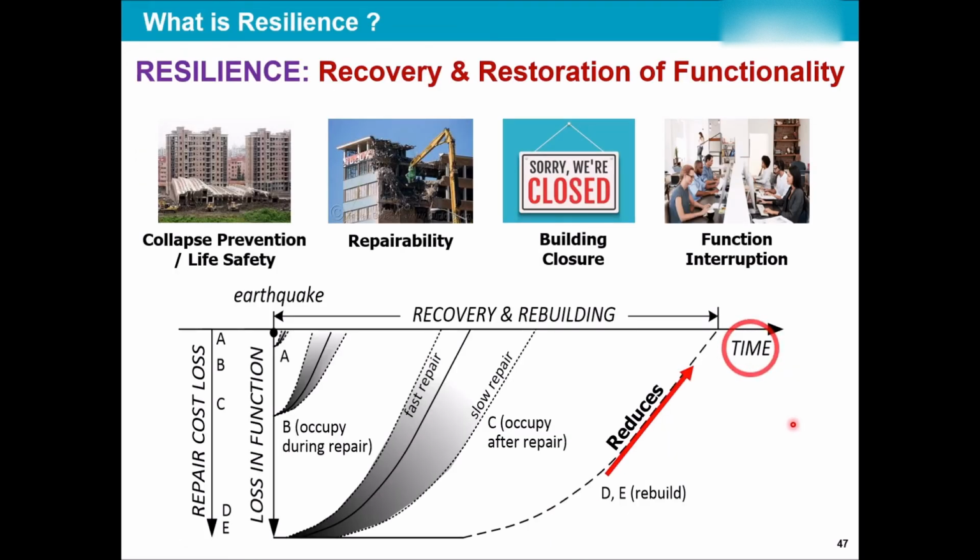One of the major concepts that you can see is continuously referred to in performance-based earthquake engineering is the concept of resilience. So in simple terms, resilience is the ability of the structure or the organization to go back to its initial operational, full operation in the most controlled possible time. So the longer this time is, the less resilient you are. The shorter this time is, your business, your building is more resilient.